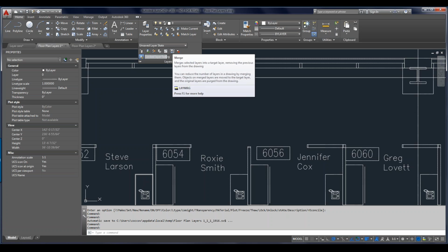But what the SetByLayer command does is, if an object has an assignment of ByBlock instead of ByObject, or if you have blocks that have colors assigned to them, it will go into those blocks and also set that to ByLayer if you give it that option. So basically it goes into the nested level, going through properties you can't get to, if that makes sense, hopefully.